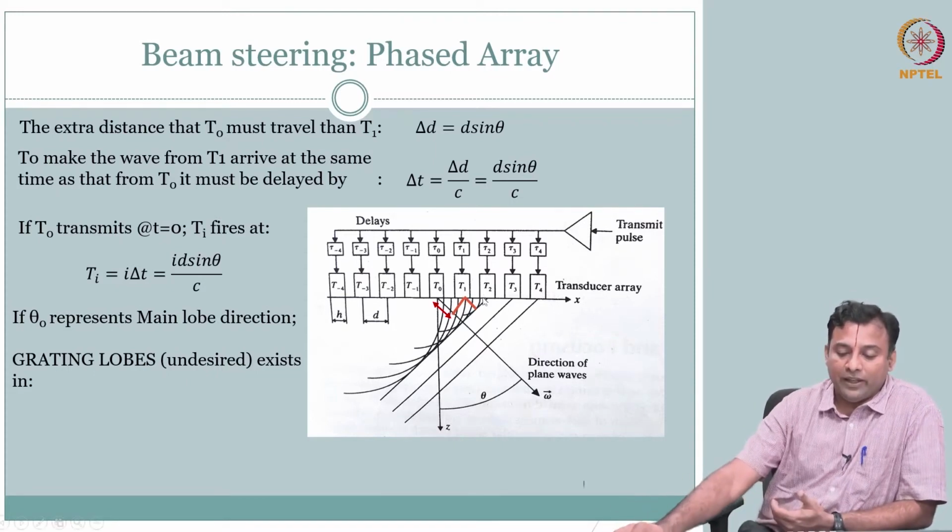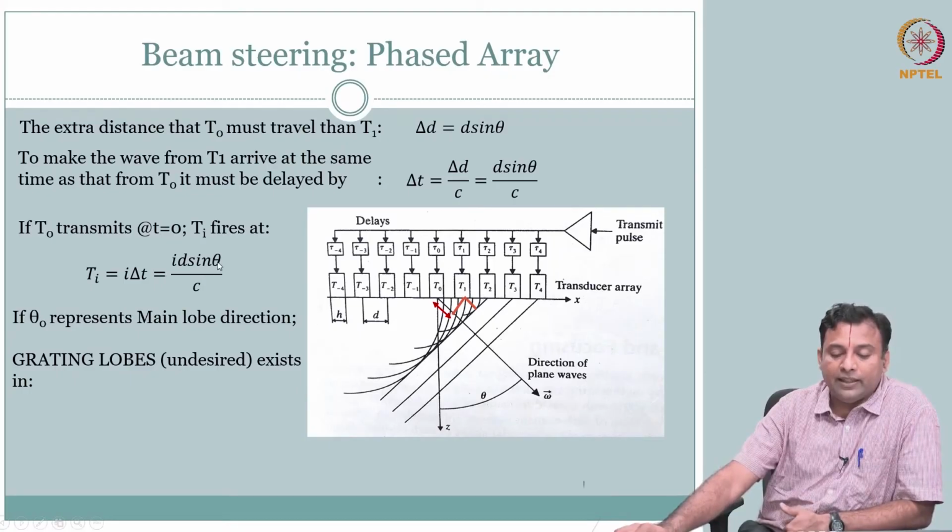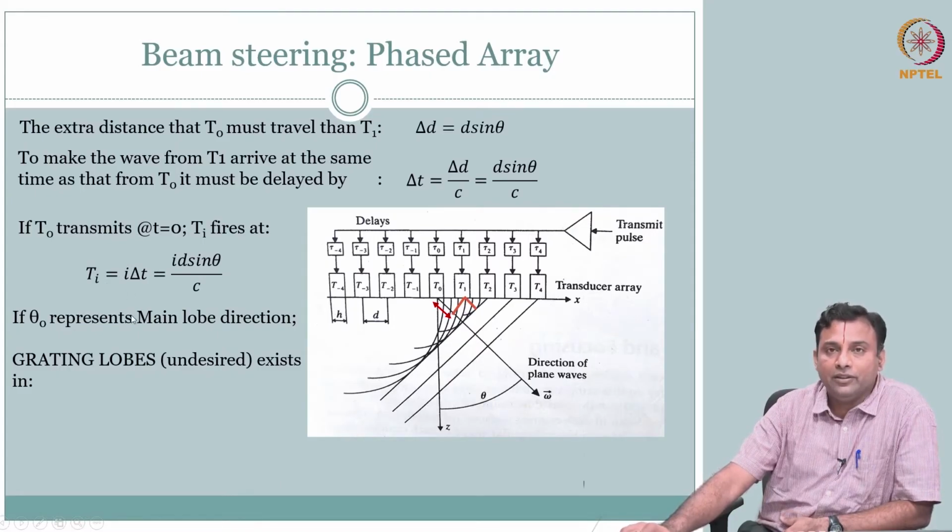Now I can change whichever direction depending on the theta. I can manipulate my excitations for each of the crystals. Each of these will be a separate channel. So you could code the corresponding delay, and you can execute this.